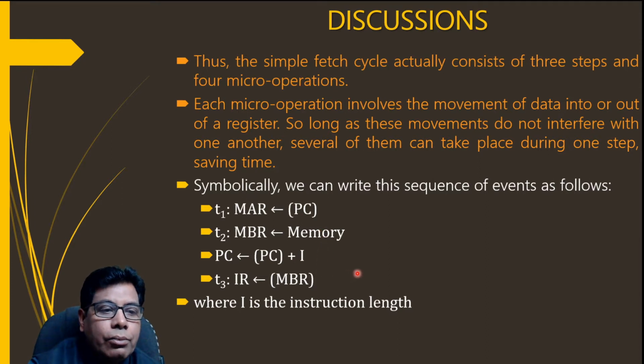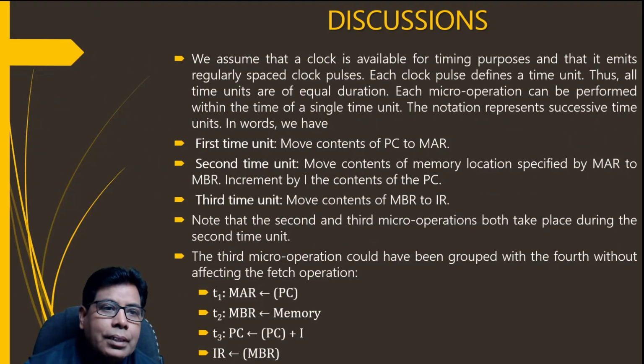Now here we see that during T2, the contents of memory are loaded into the memory buffer register, that is the opcode of the instruction is loaded into the memory buffer, and the PC is incremented by 1 or 2 depending on the instruction. So these two are done simultaneously. Then further if we go,